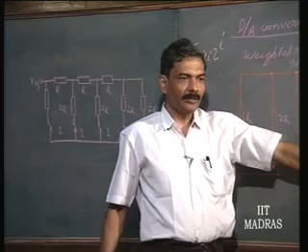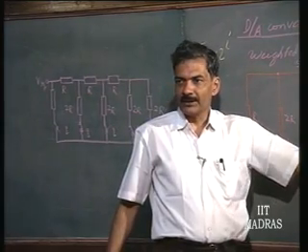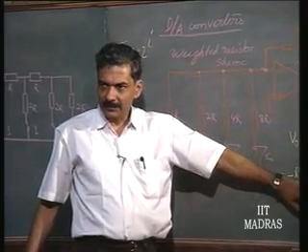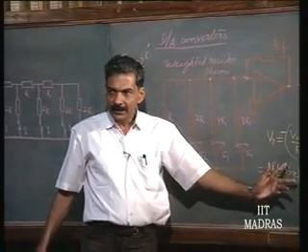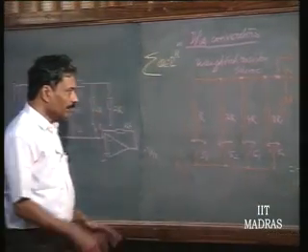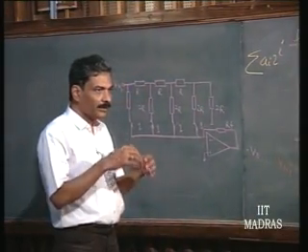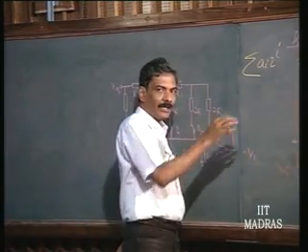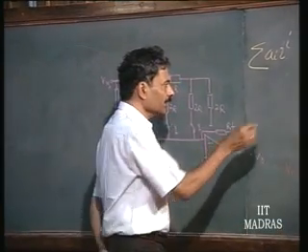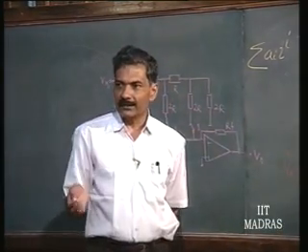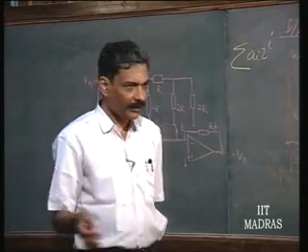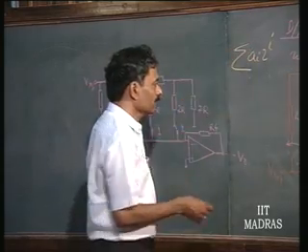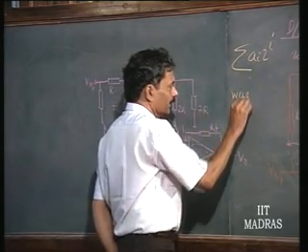These constants may vary depending upon the scheme of addition. It may be a ratio of resistors or a ratio of capacitors. If it is a switched capacitor network, it will be a ratio of capacitors. And there will always be a voltage reference. So, what are the integral parts of a D to A converter? One of the important blocks necessary to make a D to A converter IC is the weighted scheme. It could be weighted resistor, weighted capacitor, anything. It is the one that determines the weights as given in this expression.